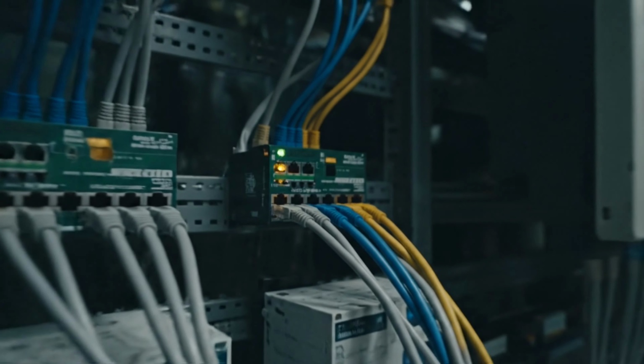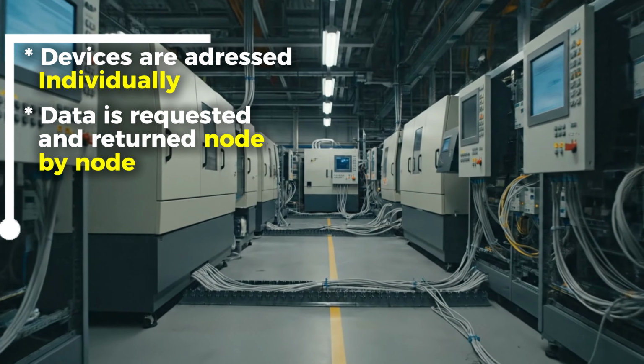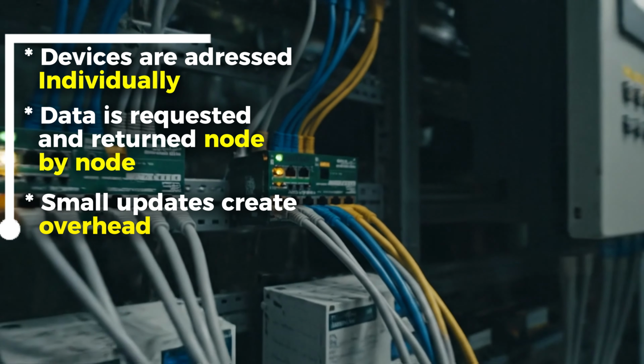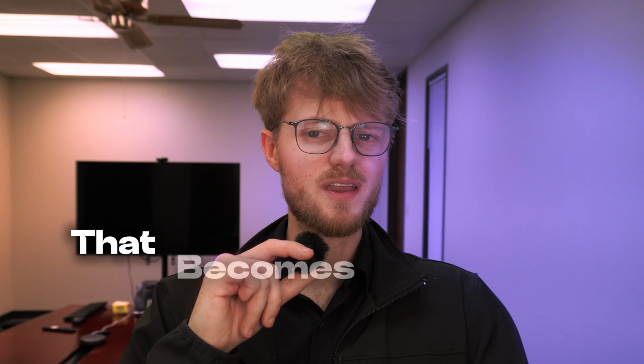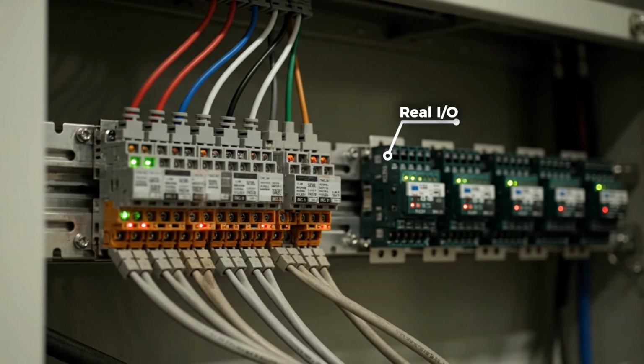Now, traditional Ethernet is great for IT traffic, but it's not ideal for real-time control. In a typical Ethernet network, devices are addressed individually, data is requested and returned node by node, small updates still create overhead, and timing can vary depending on traffic. And that becomes a problem when you're dealing with real I/O points that need predictable updates.